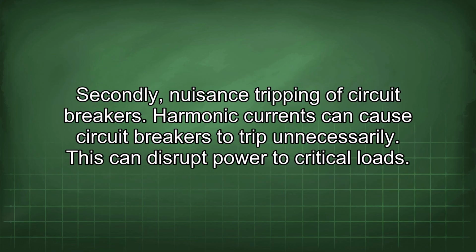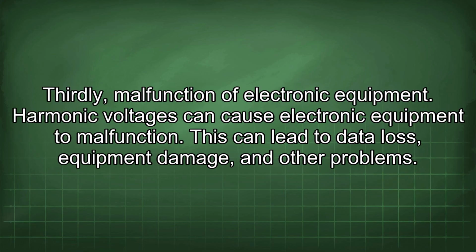Secondly, nuisance tripping of circuit breakers. Harmonic currents can cause circuit breakers to trip unnecessarily. This can disrupt power to critical loads. Thirdly, malfunction of electronic equipment. Harmonic voltages can cause electronic equipment to malfunction. This can lead to data loss, equipment damage, and other problems.